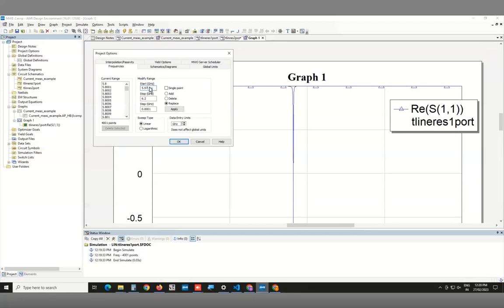So it's a very sharp resonance, and this has got to do with the value of the capacitor that was given. I saw in some cases the value of the capacitance was left to the default value, which comes when you place the capacitance from the circuit, and that would have given a completely different result. That's usually about a picofarad or something, depending on what settings you have. But I don't even understand how you can do that, because the problem says use a 5 femtofarad capacitor.